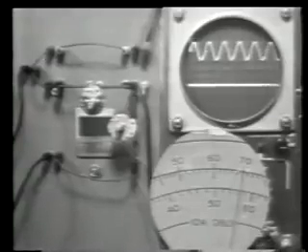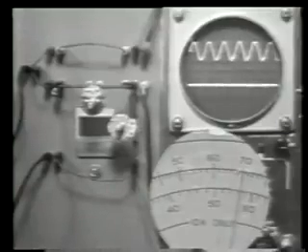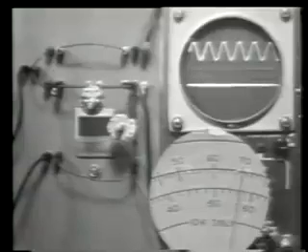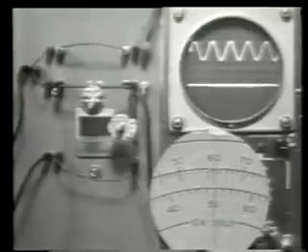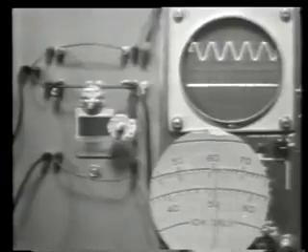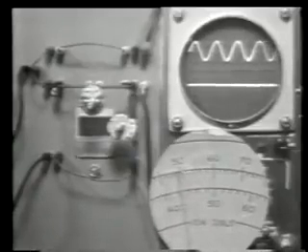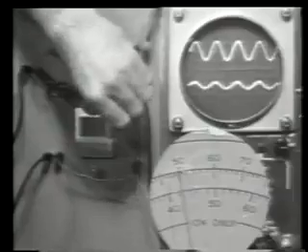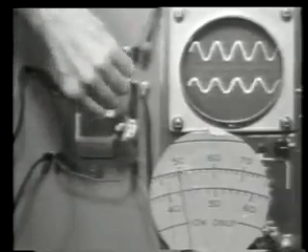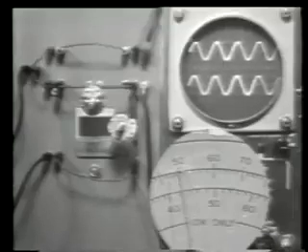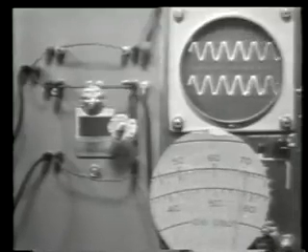We can pass or reject specific frequencies, but since resistors are not frequency-sensitive devices, this system is not very practical, is it? The circuit is now rejecting 700 hertz, all right, but it's also rejecting all other frequencies as well. If we set it to pass one frequency, say 500 hertz, by selecting maximum shunt opposition and minimum series opposition, like this, well, it not only passes the frequency we want to pass, it passes every other frequency as well.